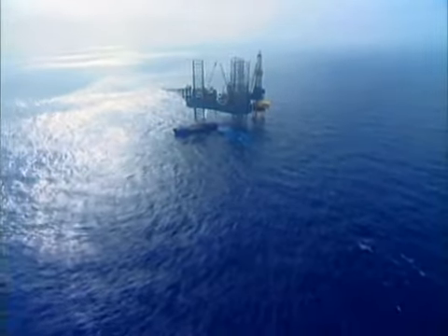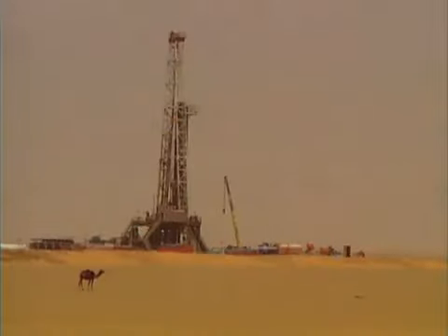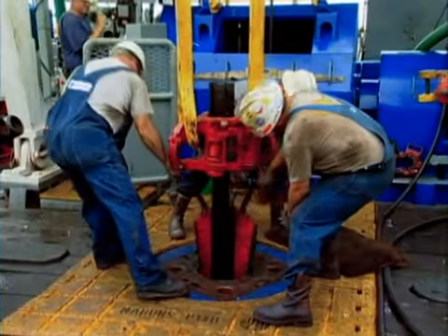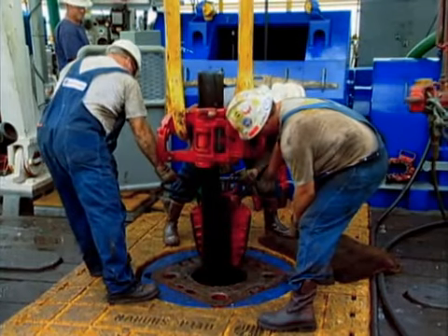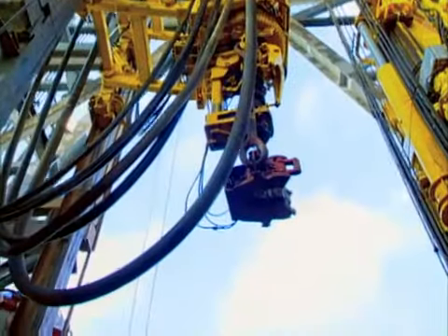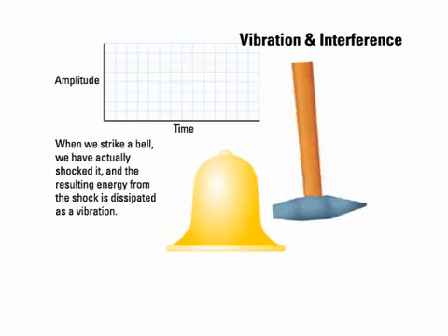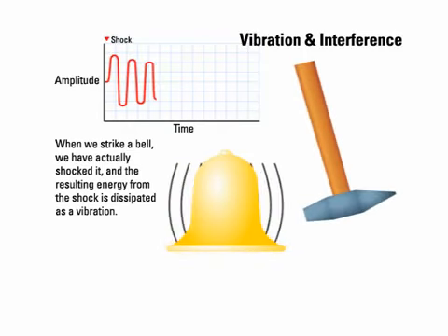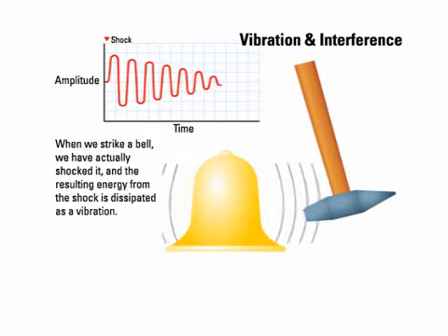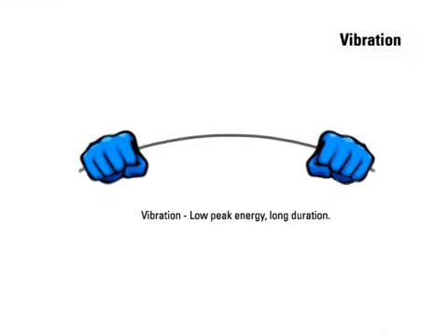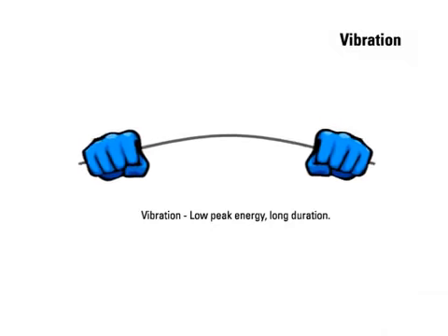As you know, both shock and vibration are prime culprits in many drilling problems. Today we are going to discuss how to minimize their effects and thereby improve drilling performance. Shock in a drilling environment is the sudden input of energy from impacts of the bit, BHA or drill pipe with the wellbore. Vibrations can result from the shocks.